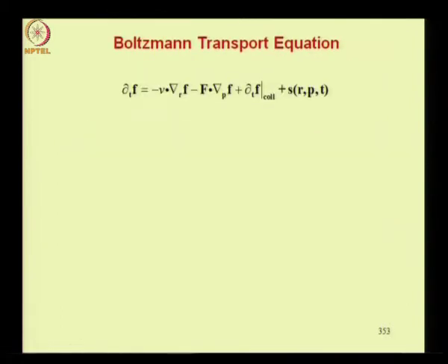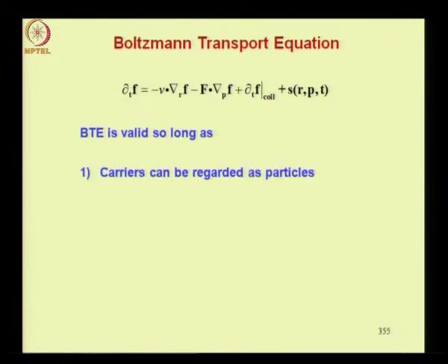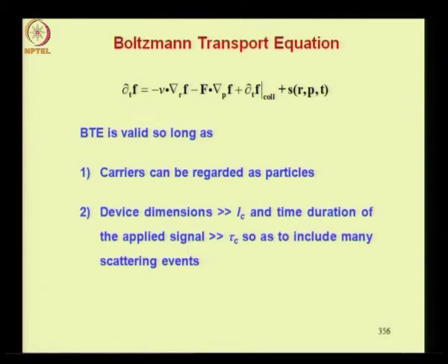Let us look at the Boltzmann transport equation. What is the range of its validity? So BTE is valid so long as carriers can be regarded as particles, for which the conditions will be discussed shortly, and 2, device dimensions are much greater than the mean free path, and time duration of the applied signal is much more than mean free time between collisions, so as to include many scattering events.